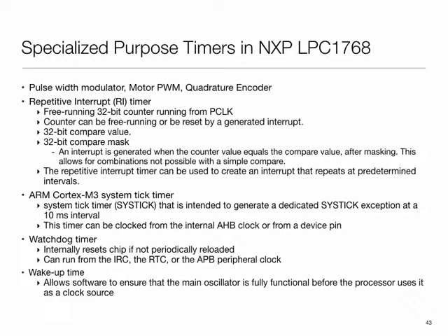And the final thing is that there are specialized timers which are meant for very specific purposes. So one type of timing signal which is very common in embedded systems are so-called pulse width modulators. What these pulse width modulators do, okay, let me ask you, anyone knows what a PWM signal looks like? It's a square wave with a variable period. Okay, so why do we want to vary it? Someone else? Yeah. The ratio of on to off basically gives you how much of the signal that you need.